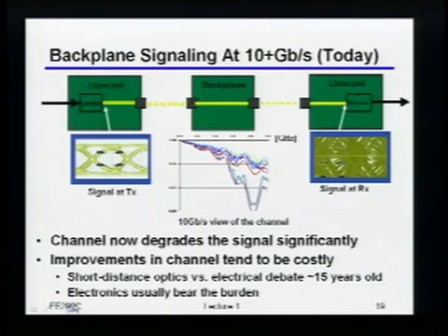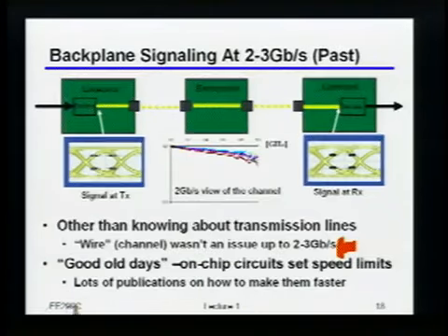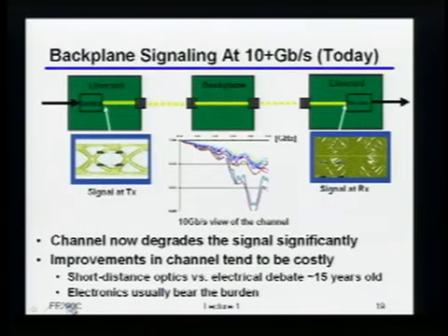Okay, so the big difference you should notice between this picture and this picture right here is, this one was a representation of the signal that I sent at the transmitter. For those of you who have seen it before, this was like the eye diagram at the transmitter. If you haven't seen eye diagrams before, don't worry, I'll explain what they are next lecture. But the key message is you can see these nice clean-looking things that I sent at the transmitter. Well, I used to get those same nice clean-looking things at the receiver. Well, now these days, if this is what you sent, this horrible, disgusting mess, which you can hardly tell what it is, is really what you'd receive at the input of the receiver.